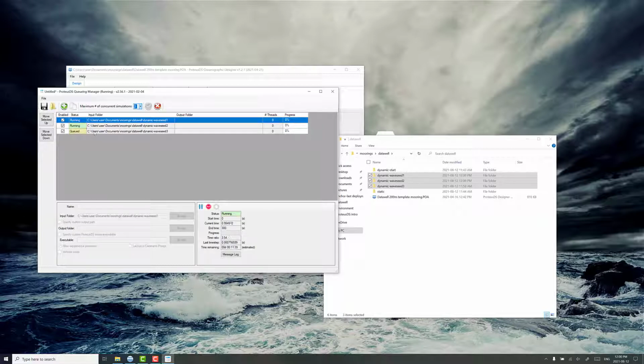And you can see this one is queued up for later, and you can get the same kind of information about what's happening with the simulations from this little window here. If there's a problem, it'll tell you the problem. You can stop the individual simulations here. This X means it'll stop any new processes from beginning, but it'll allow these ones to finish off if it can.